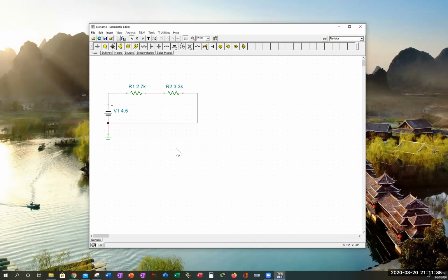Now, once you've done the wire connections, you want to make sure that everything is electrically connected and not just visually connected. And you can do that very easily by selecting a component, nudging it up. Do the wires go with the unit? Yes, they do. Bring it back down, select the next component, nudge it up. Do the wires move with the component? Yes, they do. Bring it back down, bring the voltage source, move it out. Do the wires go with it? Yes. So that means you not only have a visual connected set of wires, they are electronically connected.